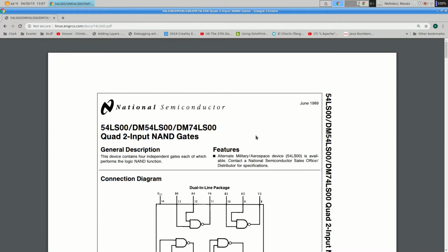You can find tutorials on YouTube and stuff like that, but if you find the data sheet, it'll tell you most of what you need to know. And you get some random board and there's little numbers on the tops of all the chips. You find the biggest chip, you look for the number on top of it, you pull up the data sheet. And there's a good chance that'll tell you how to use this board, at least how to get started with it.